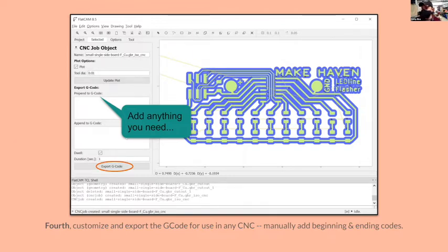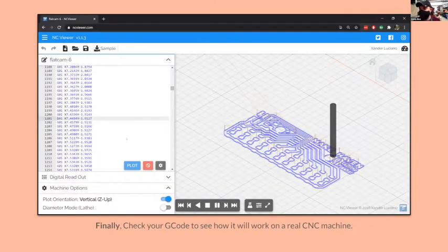Here it is in an NC viewer, a G code viewer software. This is just like you would preview on the Shapeoko. You can preview that G code, and it's very small, don't get me wrong, but it is completely G code that could be run by any of those machines. As long as your CNC has enough accuracy, precision, and low runout, you can mill a circuit board on any of the CNCs that we have.